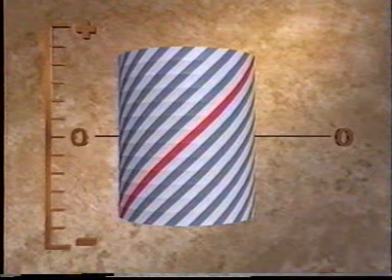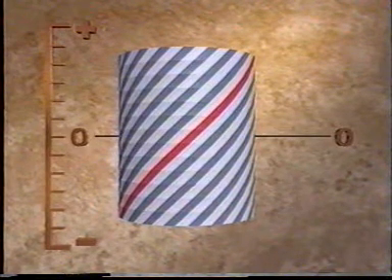When a part is subjected to a torsional stress, the fracture will normally originate at the surface, where the stress is maximum. Fractures cannot originate deep within the part simply because the stress decreases to zero at the neutral axis. When a transverse hole is added to the shaft, creating a stress concentration, the stresses increase greatly at the edges of the hole. Maximum stresses occur at 45 degrees to the axis of the shaft.